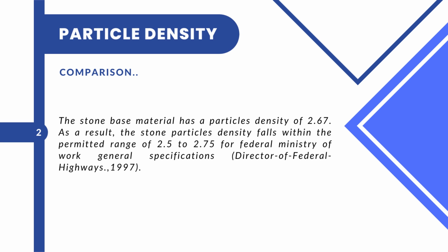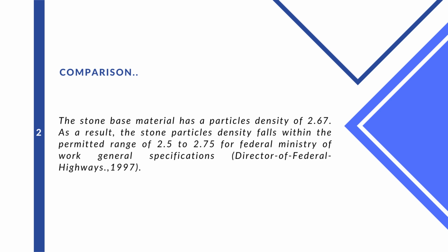So we checked the particle density. The particle density obtained is 2.67, and the specification says it is supposed to be within 2.5 to 2.75, so it meets the criteria.